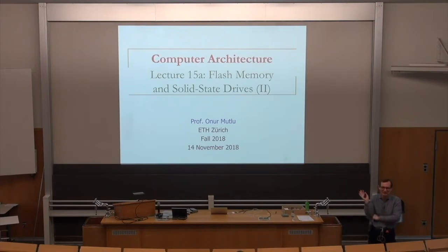Refresh is another example. PCM has a retention loss phenomenon. There's some amount of refresh that goes on in those devices also. But there's more to come, especially as these devices are analyzed. We'll understand them more. Yes. So could it be like the one-to-one mapping that we have in DRAM, where the address also gets broken up if you use PCM? In a hard disk, you have block sectors, and the SSD moves things around. Exactly, yeah. So in PCM, it could move around also, yes.